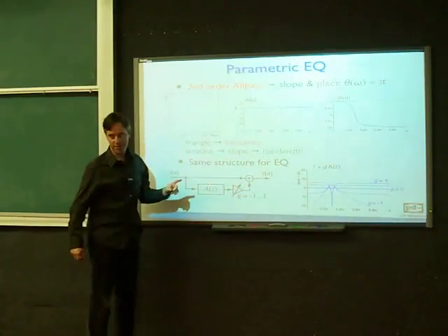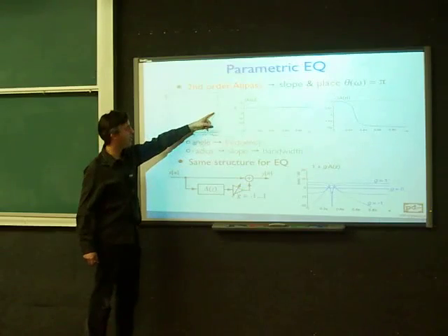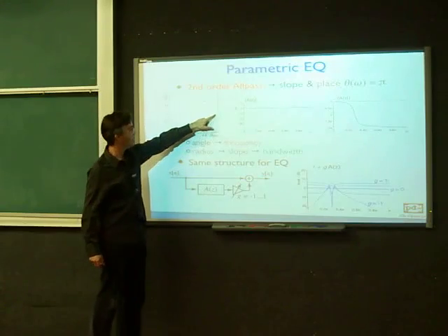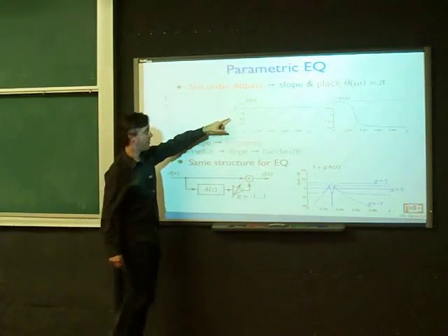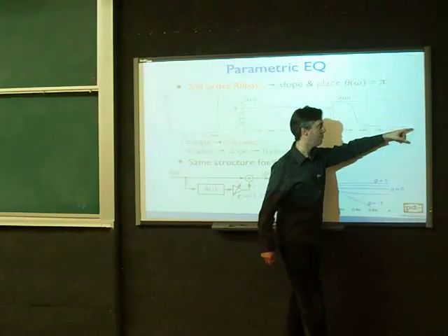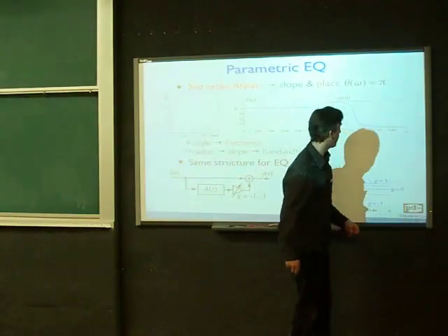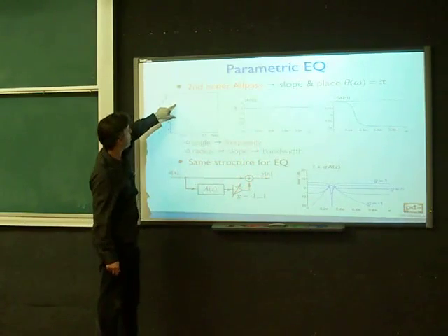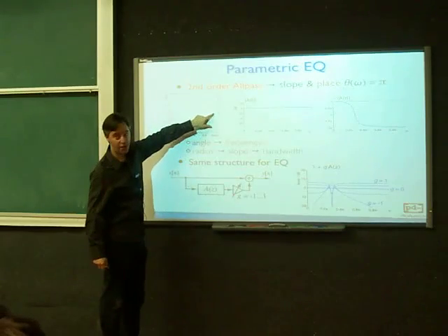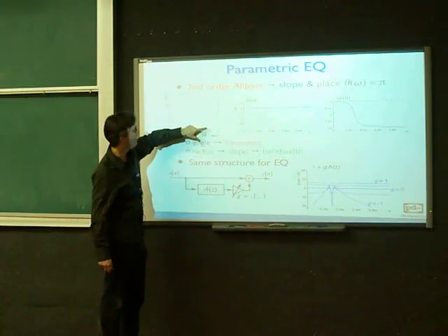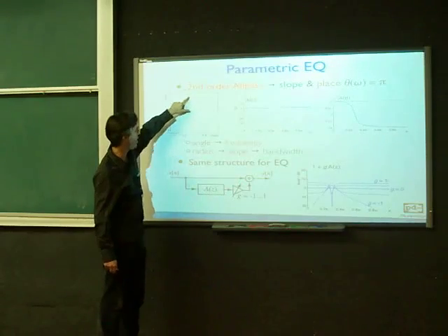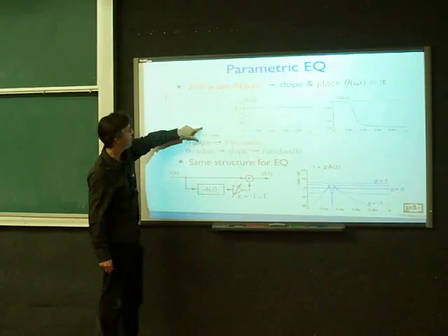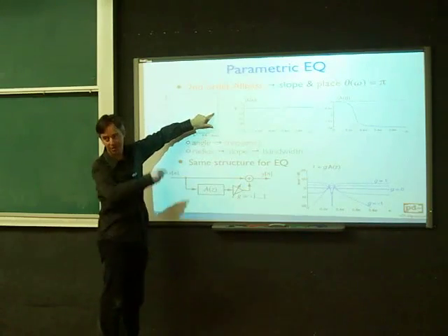It doesn't really matter too much, but what happens is if you think about the phase at this point and you go all the way around the circle, and then you get the phase at the end, which is basically going all the way out to 2 pi over here. And what will have happened is, you'll have encircled these 2 poles, an entire circle, but you'll still be outside of the zeros. So the zeros will contribute phase that will change, but at the end of the day, you'll be at the same. It'll all have cancelled out.